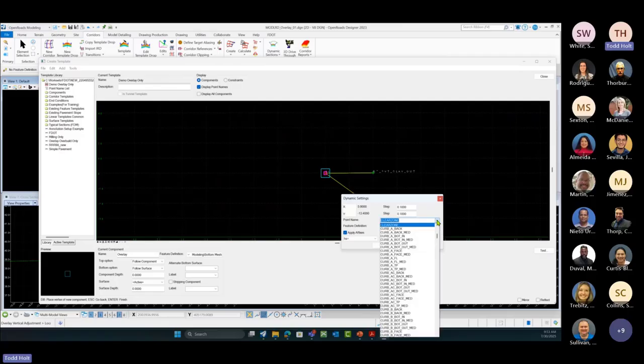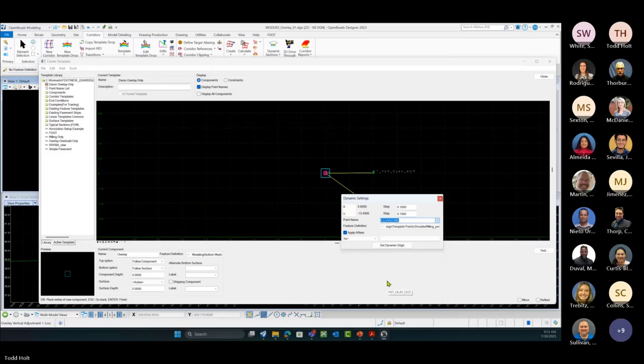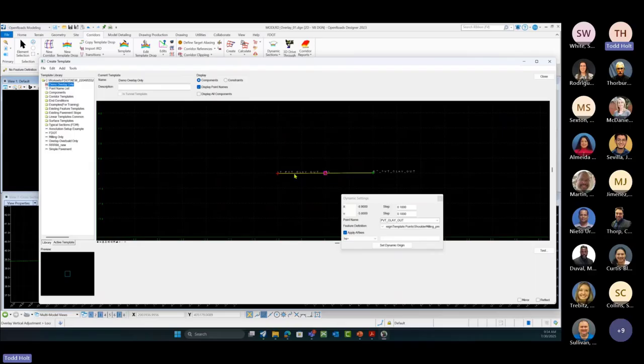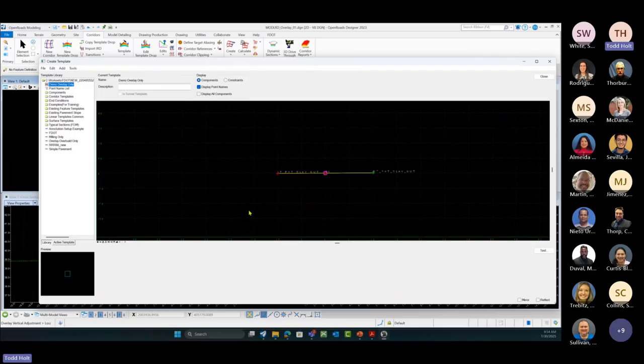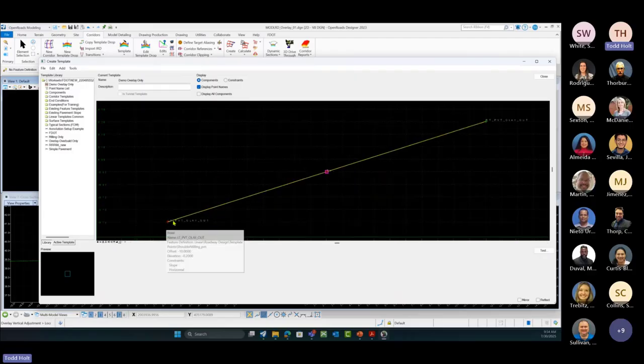And then we're going to go back to our HS. We're going to come back to our pavement layout. So we'll find that point name again. And this will be -12, 2, or -10, 2. Right, and then I'm going to hit enter, and that's going to draw it on the other side. So then I'm going to right click and finish. And there is our component that we have drawn in there. So if I hit fit view, right, so there we have our -2%.